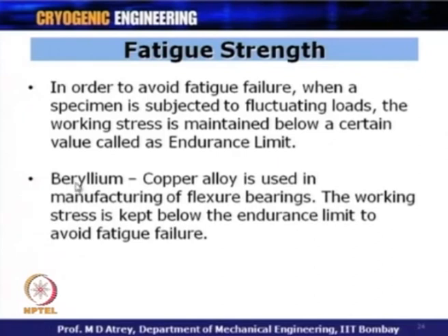The flexure bearing which I showed to you is made out of beryllium copper alloy. Here you can see a beryllium copper alloy, and this is what we call the flexure, which is used to manufacture the flexure bearing. The working stress is kept below the endurance limit to avoid fatigue failure. So, I should know the endurance limit of the beryllium copper alloy, and I should keep the stresses generated below the endurance limit of this material, which will ensure that it will never fail by fatigue.